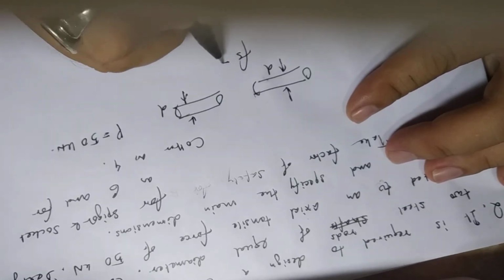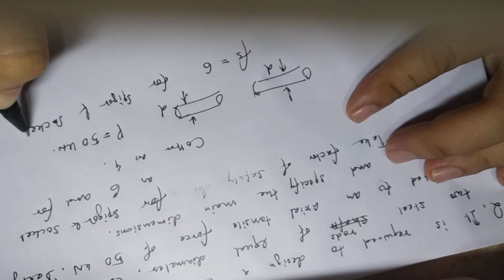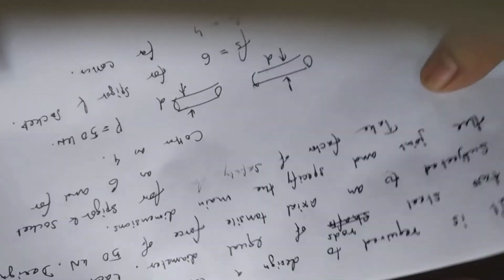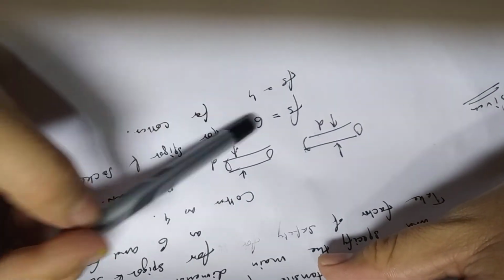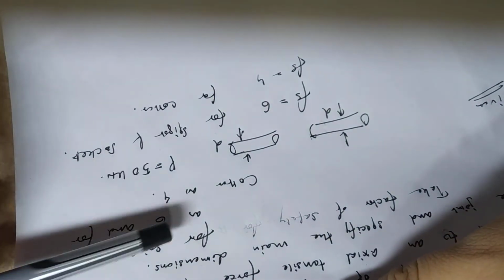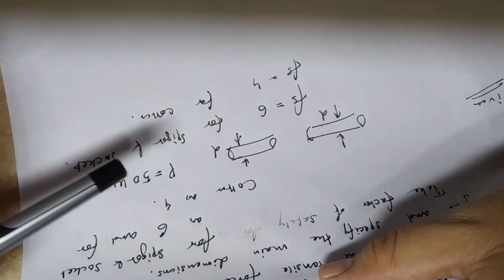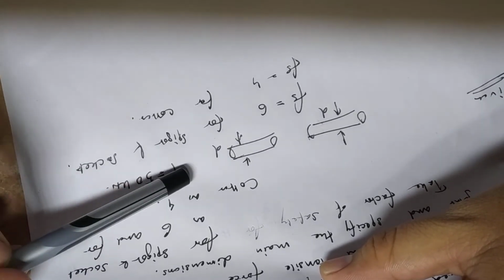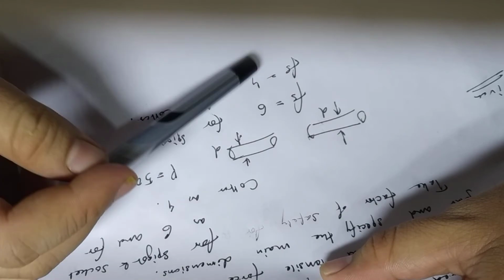Factor of safety, Fs, is 6 for spigot and socket, and Fs is 4 for Cotter. Normally, why is it given like this? Higher factor of safety means we are applying lower forces. If factor of safety is high, your allowable or permissible load is low. That means we don't want the spigot or socket to fail. If failure happens, your Cotter part will fail at the beginning, because for Cotter we have kept its factor of safety as 4.